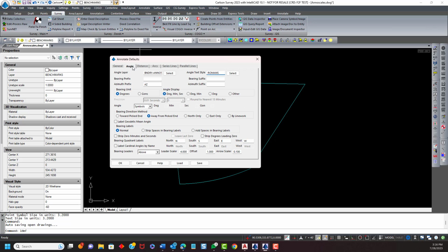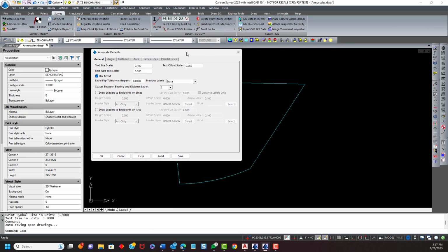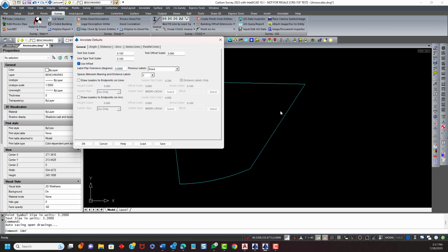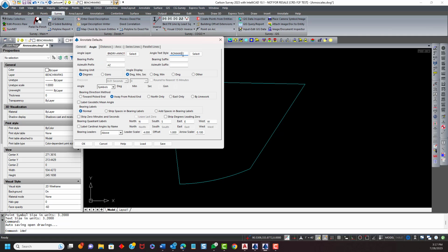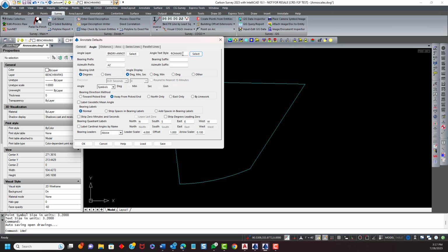What might not be known to everyone or completely understood is that this height will override whatever the text style height is. So even if I use a preset height, if I have this scalar, the scalar is going to win. So it will override any preset text heights in that particular style. So again, my recommendation is, my Roman S style, if you look at the style, it has 0 for a text height. So I don't have to worry about it stepping on the preset text height.